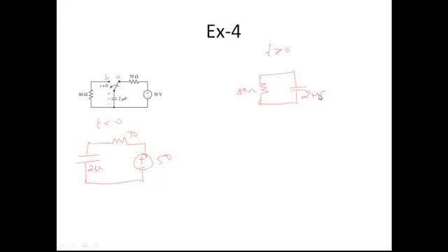Two microfarad. Okay. So in this case, t lesser than 0 will give you VC of 0, the initial voltage, which you can apply to find the final voltage value. As usual, you have to assume that before time t is lesser than 0, it is under the steady state. Therefore, the capacitance will act as an open circuit, and the entire supply voltage will appear across the capacitance. So this VC of 0 will be equal to 50 volts. Entire voltage will be appearing across this capacitance.